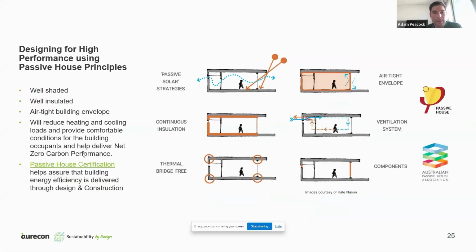That was also around about a 50% reduction in embodied carbon using just changing the floor type. When we're looking at the facades, the facades play a very important role. The facades behind the structure, they're the longest living component of a building. And there's not actually a lot of work that's been done historically to try and make facades more environmentally friendly. So I think there's an opportunity there to come up with more lower embodied carbon materials for facade systems.